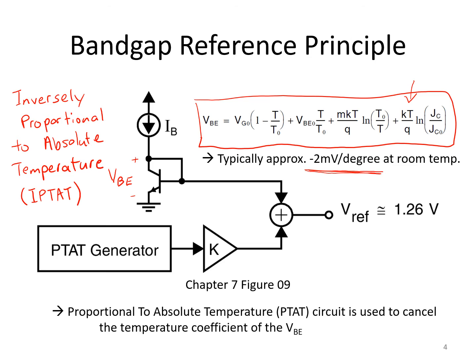For example, you can simply rely on the supply voltage itself and perhaps use a resistive or capacitive voltage divider between the supply voltage and ground to produce a reference voltage. Now, such references will vary with supply voltage variations and temperature variations, but in any case, you have to think about how accurate your voltage reference needs to be. But let's say that that's not accurate enough.